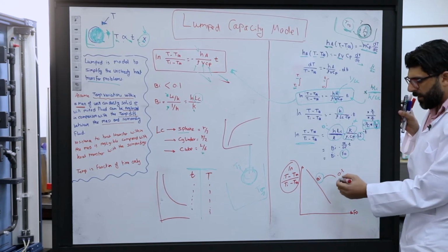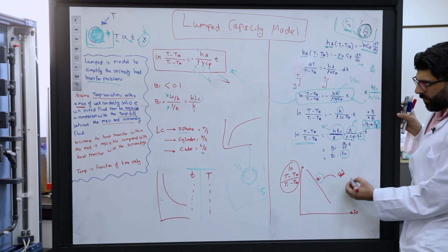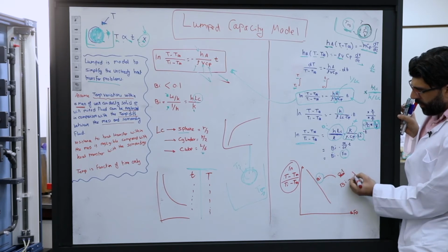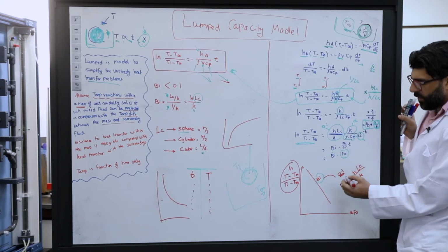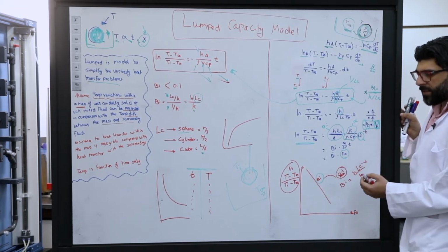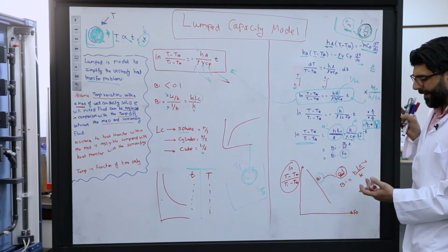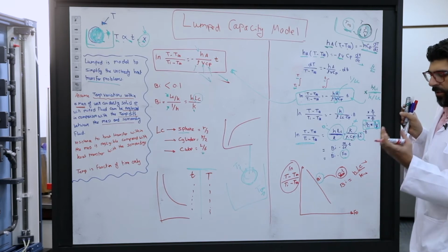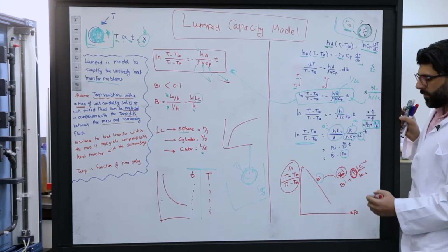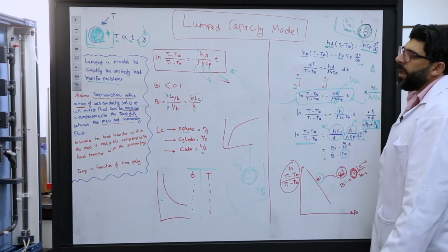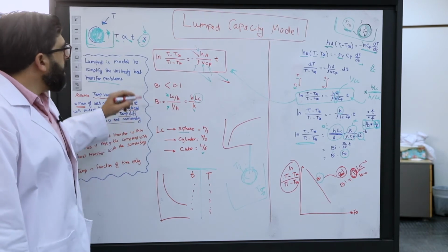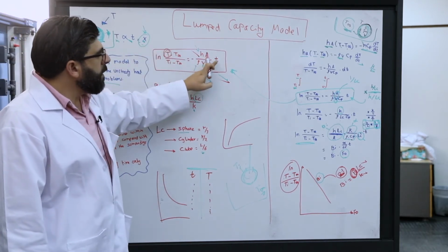Since it's applicable, and I have the Biot number, we can say the Biot number equals H LC over K. I get this value from the slope, and LC is known because it's the characteristic length, volume over area, and K is the conductivity of the shape itself, so I can find H. Once you get H, you can apply it here to calculate the time at different temperatures.